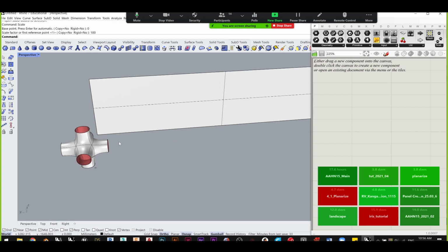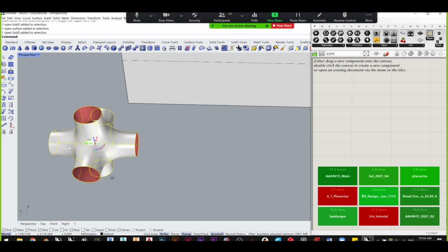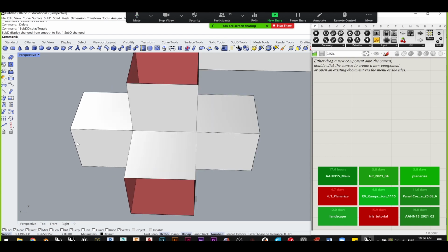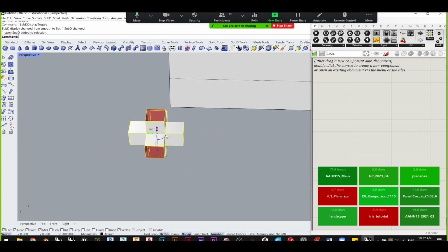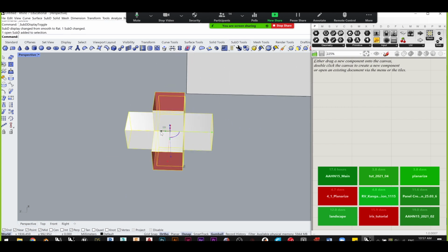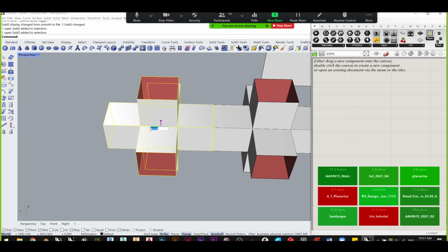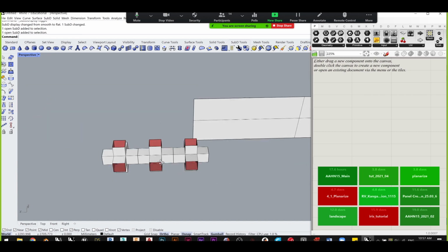Right? Now I want this to be placed on this, and basically to be copied, right? So if this is 10 and this is 10 and this is 10, the length of my element is 30, right? So I can select this element. I can click on any arrow, holding down the Alt key, and I can type in 30. But I scaled it up by 100, so it's going to be 3000 rather than 30, right? So 3000, 3000, and I end up with a chain like this.